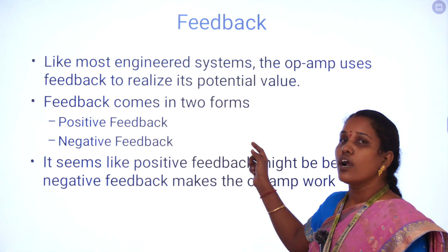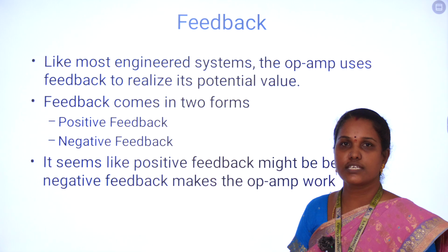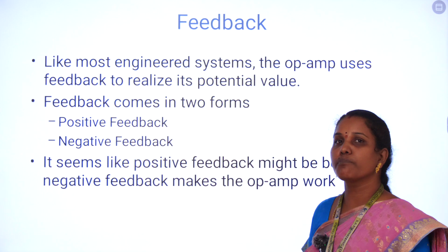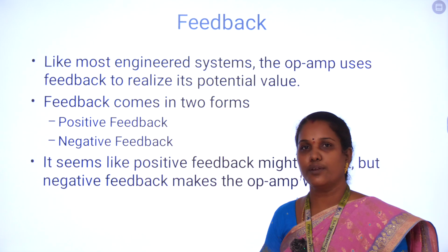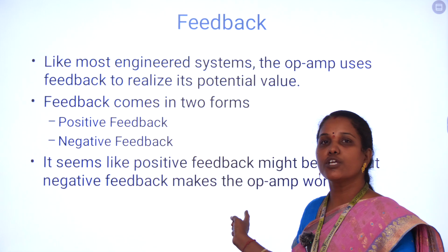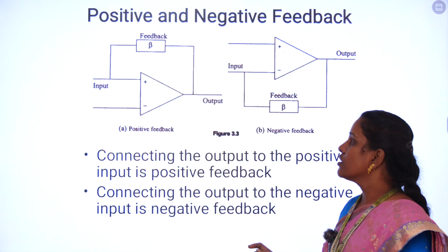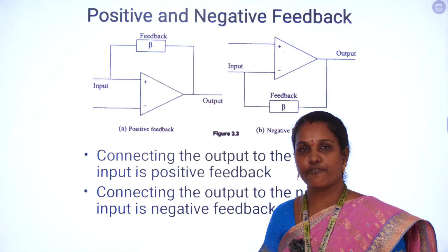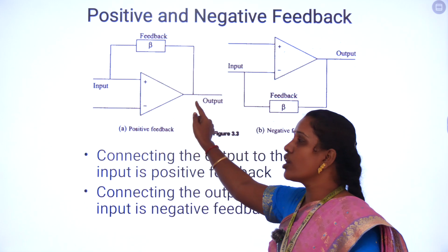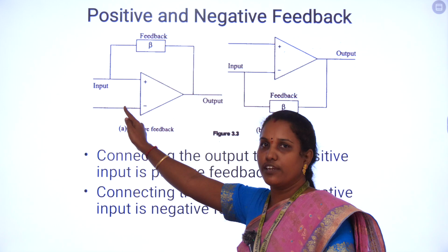Not only frequency compensation, we can also use a feedback mechanism for the stability of voltage gain. Generally, feedback is nothing but the output being given to the input terminal. A partial output is given to the input terminals. It may happen in two ways: one is positive feedback, another is negative feedback. In the IC741 operational amplifier, positive feedback is when part of the output is given through the feedback network to the non-inverting input terminal.